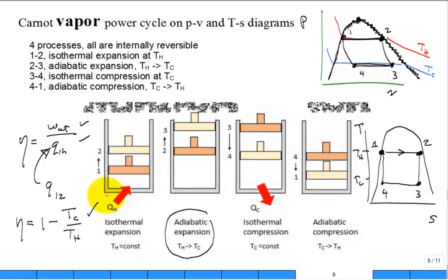It'll work. Are both of them the actual efficiencies? Like none of them are the efficiency max? Yeah, that would be the absolute maximum efficiency for that high temperature in and that low temperature out. For both of them? They're both maxes? Yeah. If I change and I boost, let's say, the boiler pressure and I change the temperature, well, then the theoretical efficiency went up. The maximum Carnot efficiency went up. But if I just analyze.